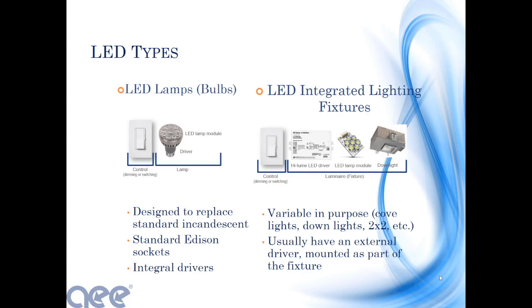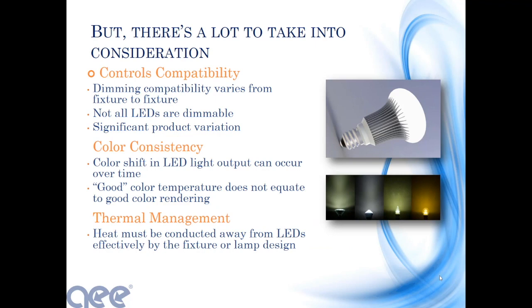Okay, so usually the driver is externally mounted depending on the load requirement. So you may have on a commercial fixture the driver in the fixture for smaller loads, but for larger loads, you may have the driver external to the fixture for the heat issues and things like that, and just getting that amount of wattage to the fixture. Okay, so there's a lot to take into consideration when you are looking at LEDs. Okay, we've talked about controls compatibility. The compatibility varies from fixture to fixture.